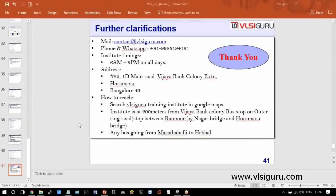So that is where front end and back end come into the picture. Front end guys do all this and give it to the back end. What we do is the backend portion of it. Meaning, start from the netlist, take it into floor planning, placement, routing, CTS, do all the timing checks and give it out. And that's still a lot of other backend activities.